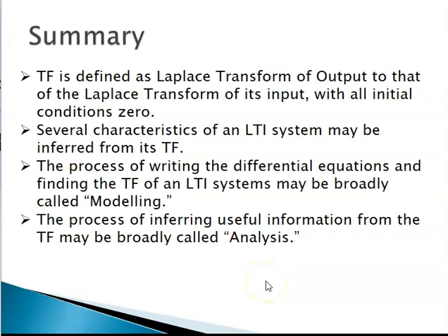That's all we are going to see in this video. To summarize, we can say that TF is defined as Laplace transform of output to that of the input with all initial conditions 0, that is with system at rest. Several characteristics of LTI systems may be inferred from its TF. So writing the equations and deriving TF is an important part in design and analysis of control systems.